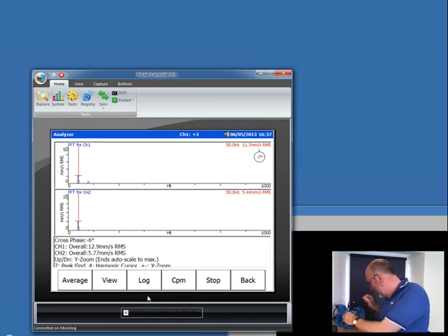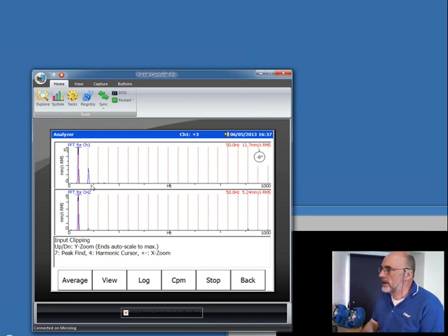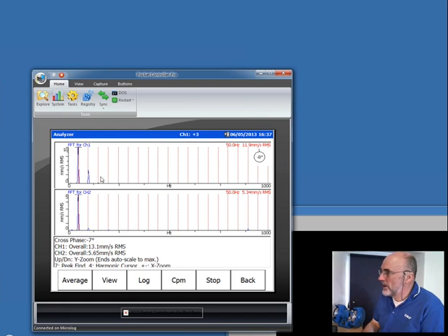So you should see, with a bit of luck, on the upper trace now, there we go. On the upper trace, you can see that we've got a high 2 times. How do I know that's a high 2 times? If I put my harmonic cursor on the running speed, 2, 3, 4, and so on, that peak is the 2 times.